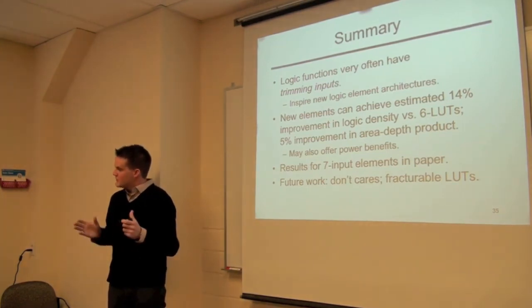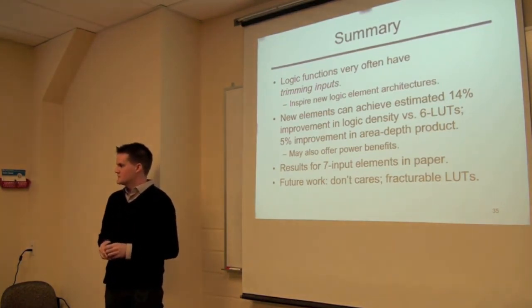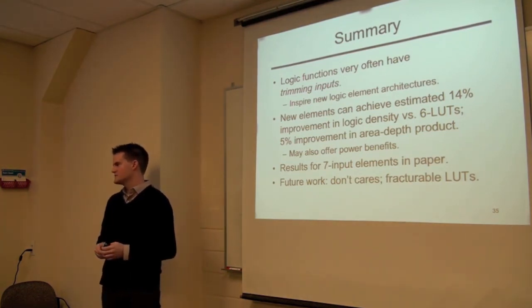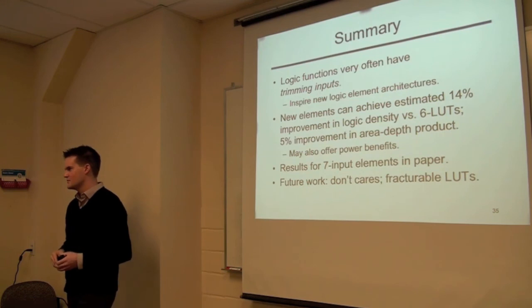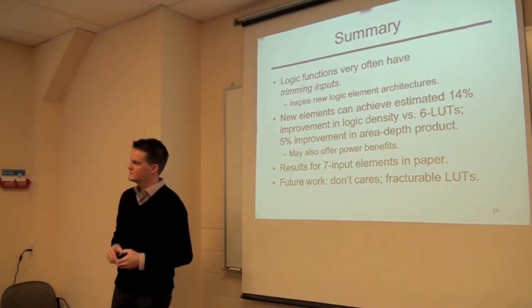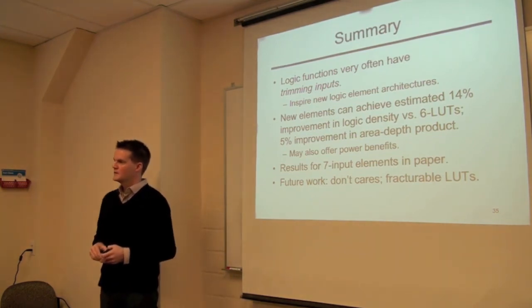It's not just the LUT RAM. Also, the size of the multiplexer is also reduced, right? So it's the whole LUT, and the size of the multiplexer is reduced in the same proportion as the number of SRAM cells. These are the multiplexers inside the LUTs, but not the multiplexers inside the block itself that do the internal wiring.